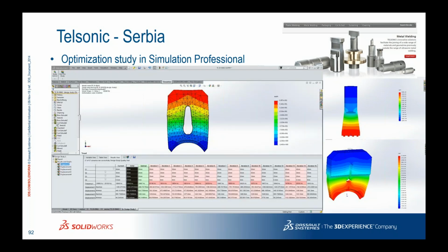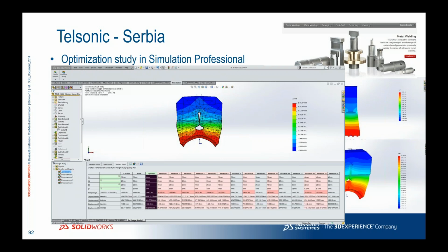They ran an optimization like we saw with Alessandro, and they found an optimal solution. This was run in some minutes, let's say 30 or 40 minutes, no more. So you can see something like 15 iterations. After that, you can check the resonant frequency that is very near to the 20 kilohertz that you want, but also it's in the Y direction, that is the most important thing that they like to have.